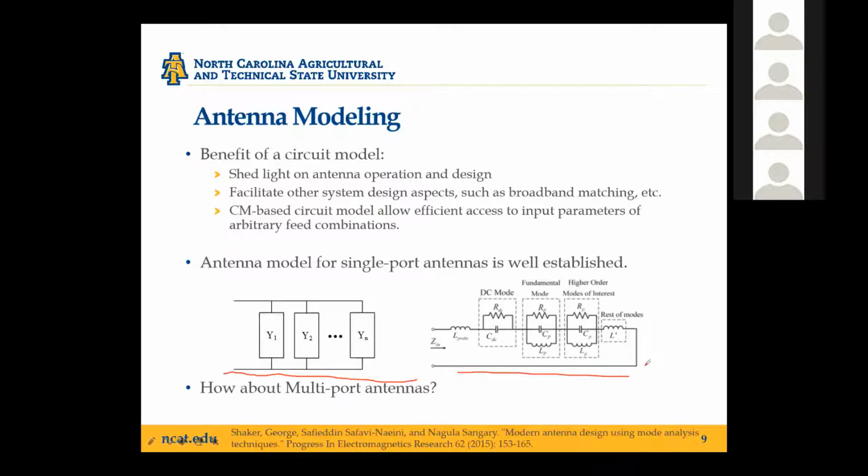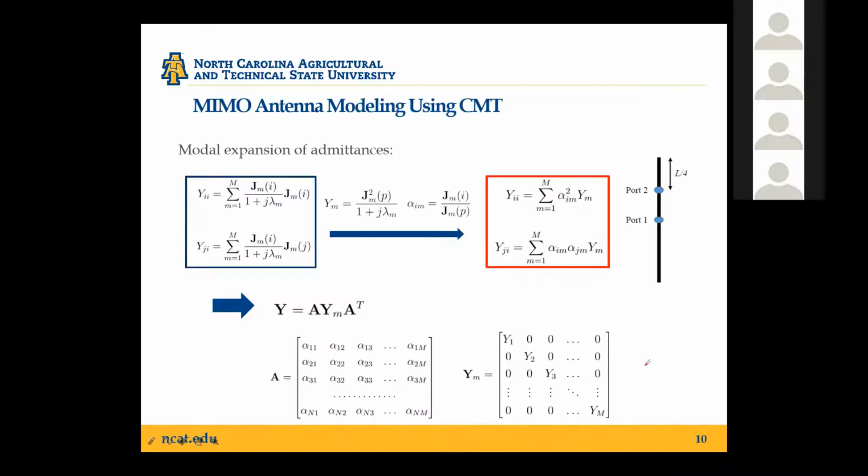So basically, you have a matrix with each entry being a function of frequency. If you think of just a random optimization in ADS or something, it's pretty difficult. But with characteristic mode theory, it turns out the physical insight helps a lot in this case.